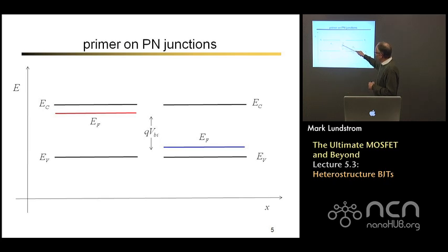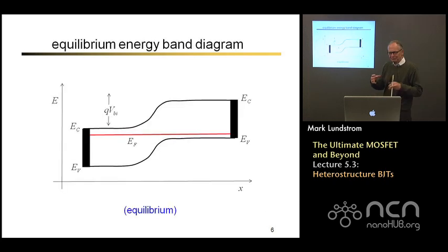Those Fermi levels are separated, so when we put them together, the charge will flow from the higher Fermi level to the lower Fermi level. Electric fields will get set up. A potential difference will get set up. That will align the bands and bring the Fermi levels equal, and that will lead to a built-in potential. So when we get all done, conceptually we think about putting this N-type layer and P-type layer together.